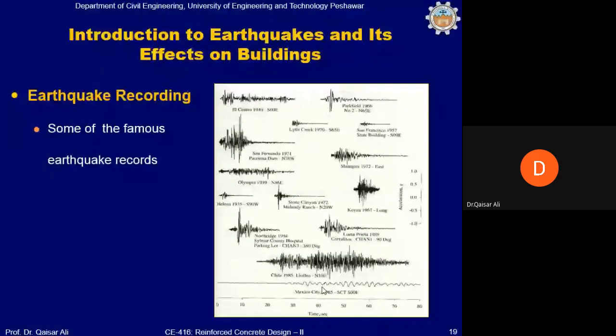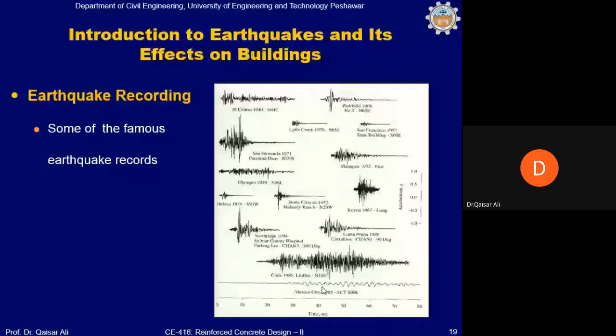Due to this earthquake, 350 kilometers away from the epicenter, there were many tall buildings whose time period coincidentally matched with the time period of this earthquake, thereby damaging the structures. It is a typical classical example of far field earthquake frequencies matching with the frequency of the structure.